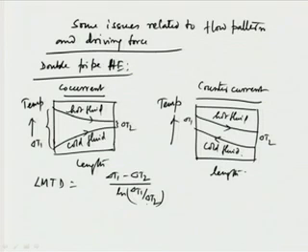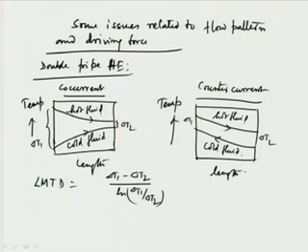Now, it's a very common question. We all know that counter current is better performing, and a counter current heat exchanger is preferable. The reason is, first, that in counter current, the outlet temperature of the hot fluid doesn't decide the outlet temperature of the cold fluid. So we can increase the outlet temperature of the cold fluid even more than the outlet temperature of the hot fluid. That is not restricted.